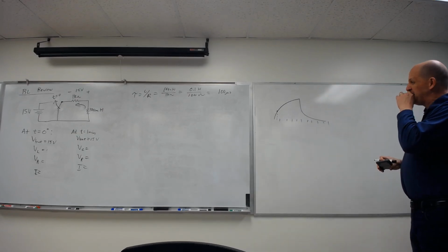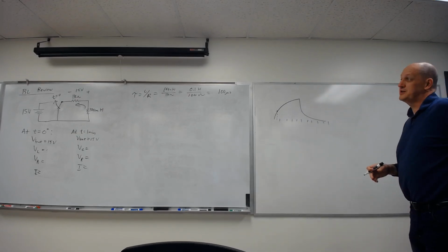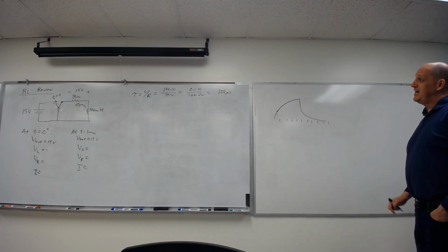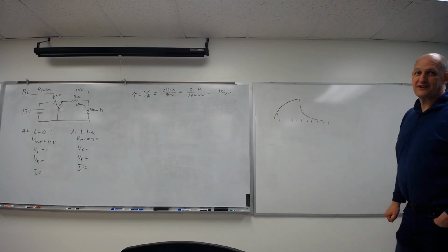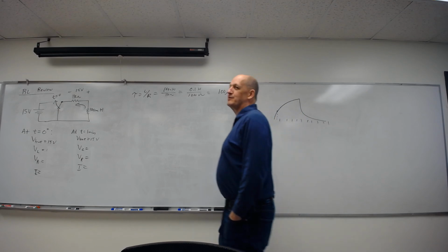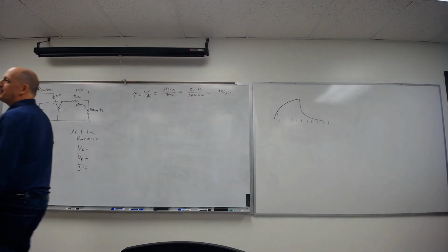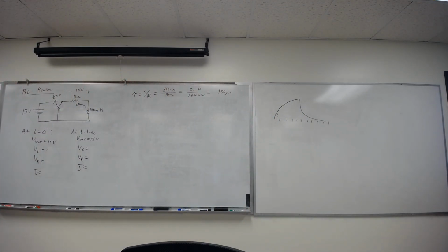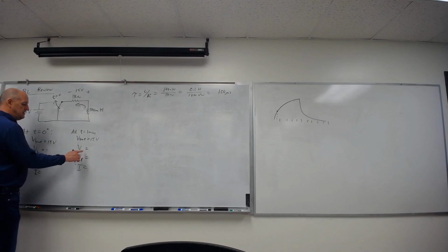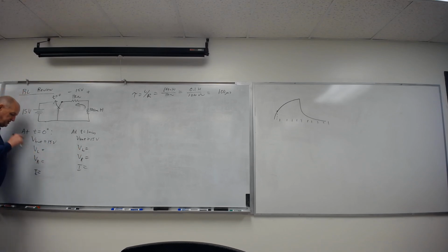So, for example, if I wanted this to have a time constant of 1 second so I can see it, I'd need like a 100 milliohm resistor, which would put lots of current through the resistor, and then I'd have other problems. So, you had to play with it last week combined with the capacitor. All right, anyhow. So, capacitors or inductors do not allow an instant change in current. The current was 0 before I closed this, therefore the current is still 0.